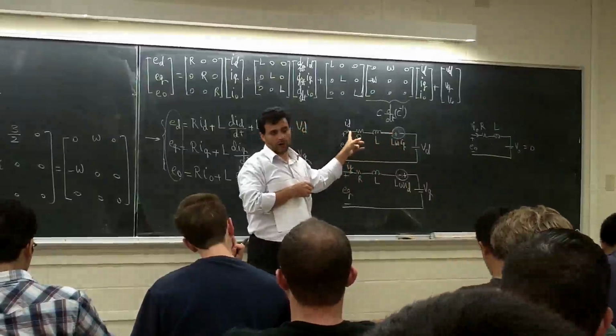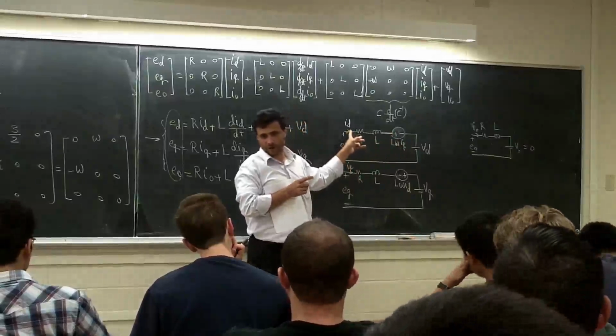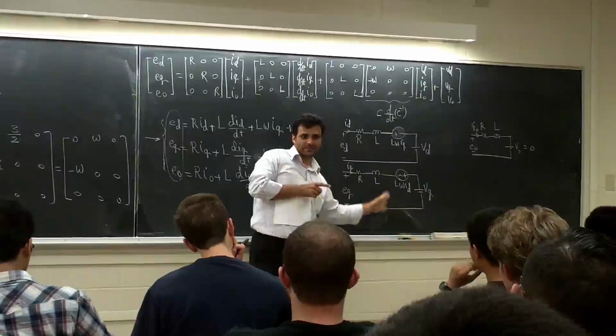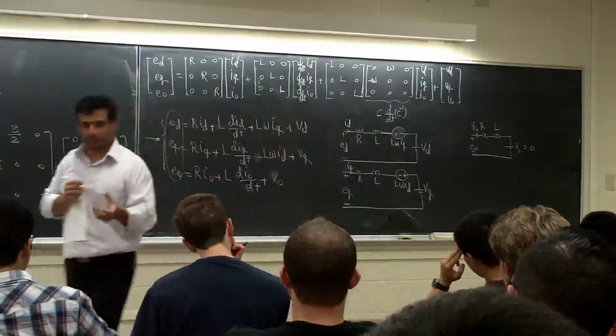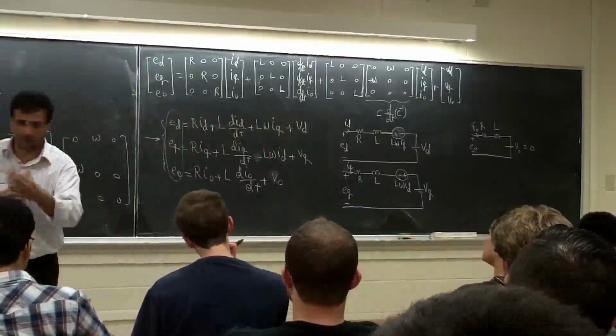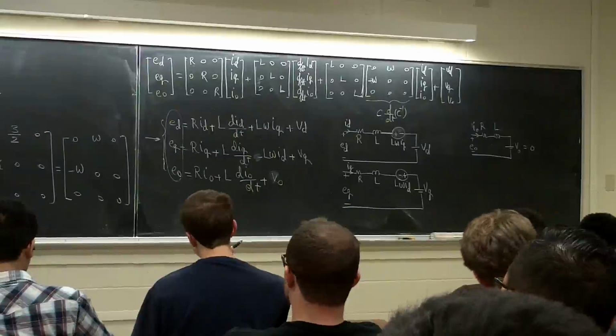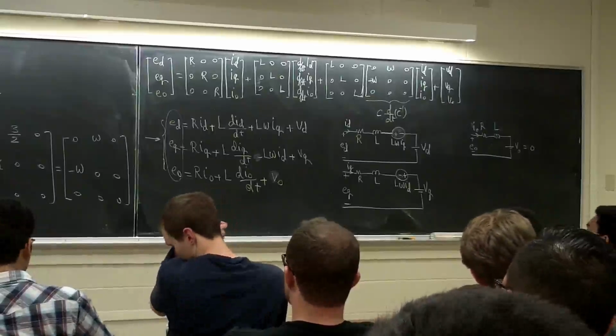Or if I want to control my reactive power, I'll change my Q value, which means the ID value is going to affect this one. Basically, these two are coupled. There is a coupling term. When you take this one this way, it's going to move that one a little bit. It's going to get stable at the end. But they are not independent from each other. They are not decoupled from each other.